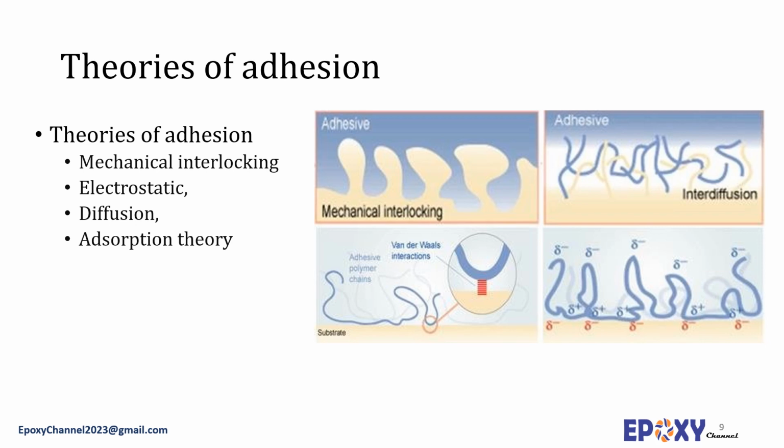The excellent adhesive properties of epoxy is often attributed to this mechanism, and that's because of the presence of pendant hydroxyl groups which exist within the molecular structure of most epoxies. These pendant groups are capable of interacting, for example, via hydrogen bond formation with hydroxyl groups frequently found in abundance on most surfaces. Primary covalent bonds can also occur during adhesion by the process of chemisorption.